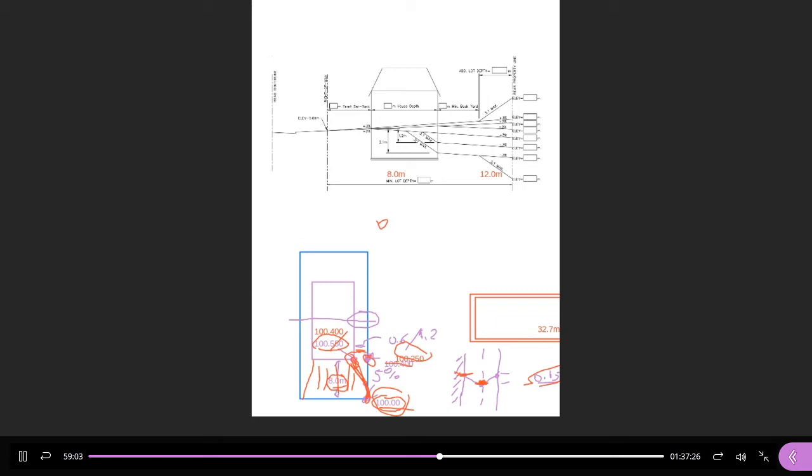So imagine the difference. You know the drawing you're preparing for Friday? If you have an elevation at the front and you have an elevation at the back, say your existing ground is up here somewhere, then the way you're going to design it is you're going to go from the front to this point here, up at 3%. Then from there, you're going to go to the back, up 3-to-1. And then to make up the difference, that's as high as you can go before you need to put in a wall. You're going to need a wall here to get up to the existing ground.